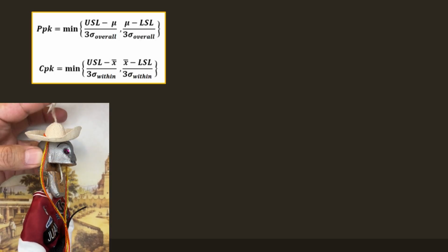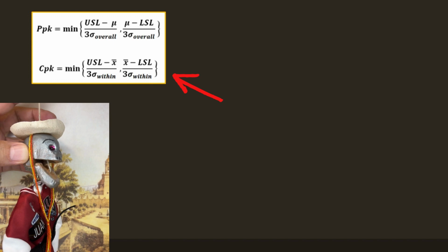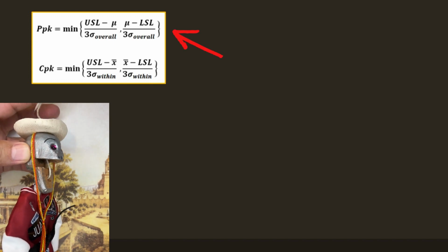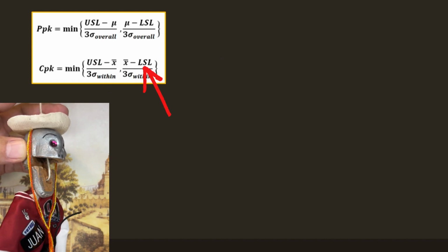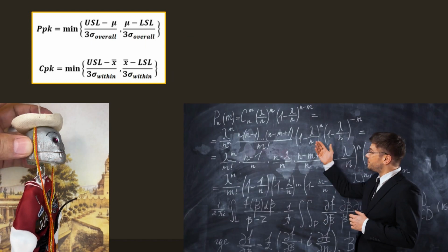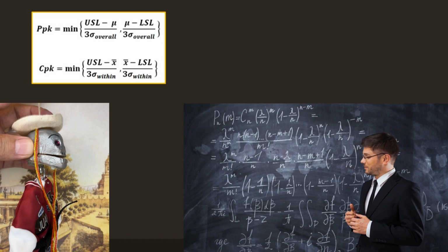To calculate the upper and lower specification limits, or print tolerances, we can use either the CPK or the PPK formulas and calculate the limits in reverse, hence the name reverse capability. In other words, we are going to use basic algebra to establish a new formula.